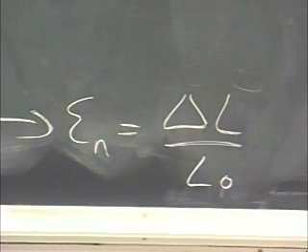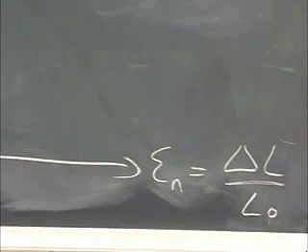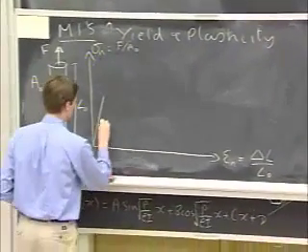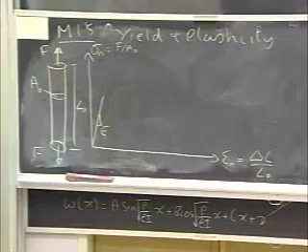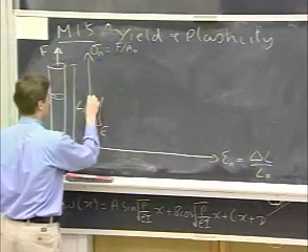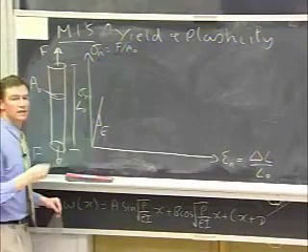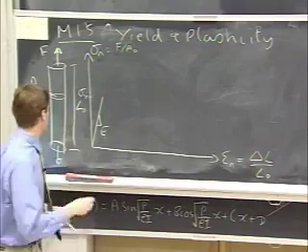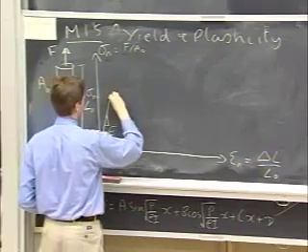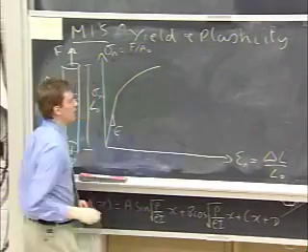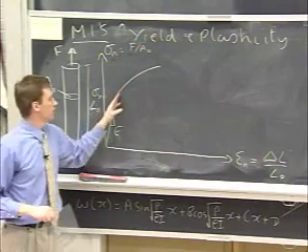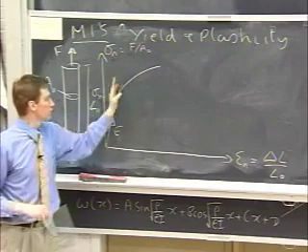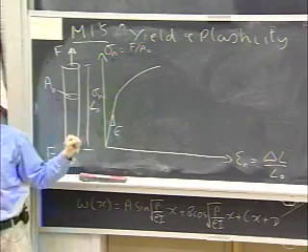What we're going to typically see for a metal is that there's some region in which it's elastic, with Young's modulus E. Then we hit a region where we get plastic deformation, we get yield, the so-called yield stress, sigma y. After that point, we get a nonlinear increase of stress with strain, but with a slope that's significantly less than the Young's modulus.